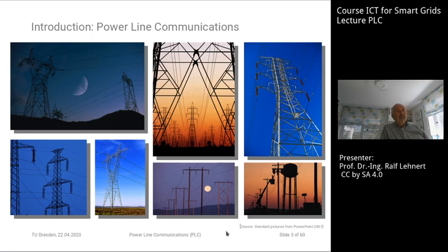Of course, this is only a country's backbone network. In power transmission we have 3 hierarchy levels. This backbone level of high voltage lines. Then in a regional area, for instance in a bigger city or in a rural area, we have a so-called medium voltage distribution network, which is, at least in Germany, typically at a voltage level of 20,000 volts or 20 kilovolts.